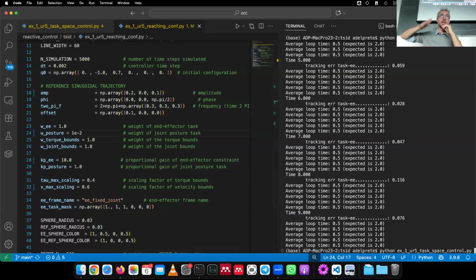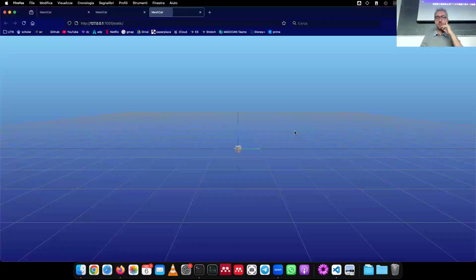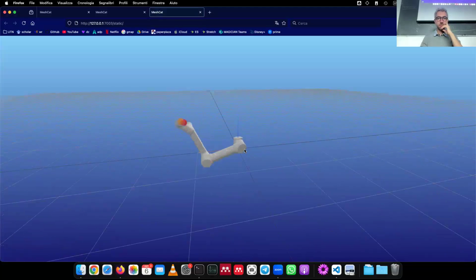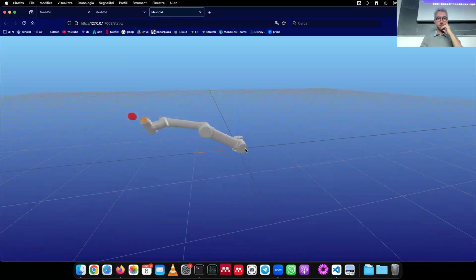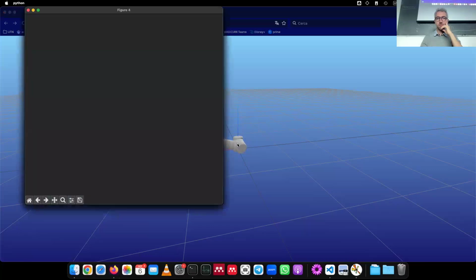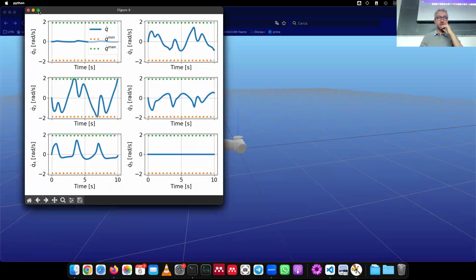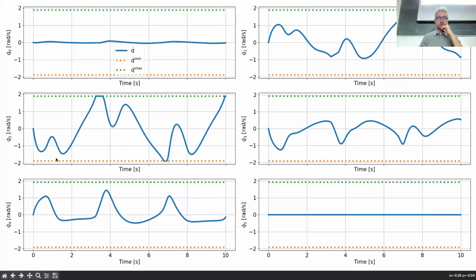And that should help stabilizing the motion of the robot, because basically that's a task that is asking the controller to maintain the robot fixed. Let's see. It is helping. So these are the joint velocities. And again, we got rid of the high frequency oscillations. So that's good.